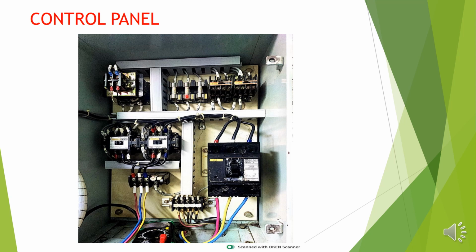Okay, if you check the primary voltage is okay, then the secondary voltage should be 220 volt. You can see this white and black cable, 220 volt power should be there. If you find that the primary has 440 volt power and the secondary doesn't have 220 volt power, it means the transformer is faulty. Okay, after the transformer there are two fuses, F2 and F3. So you have to check the F2 and F3 fuses.